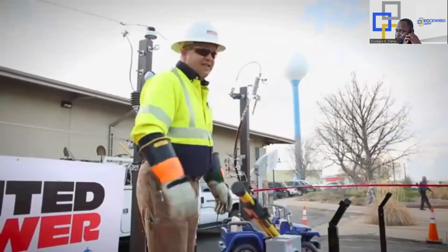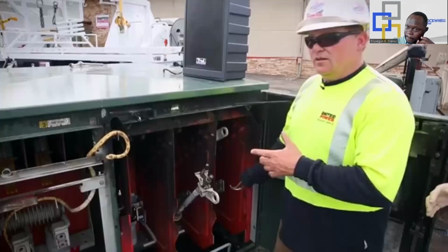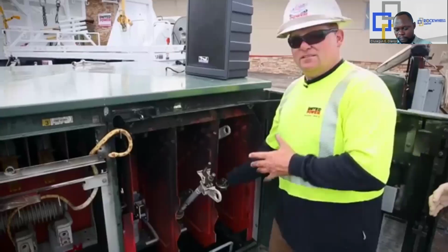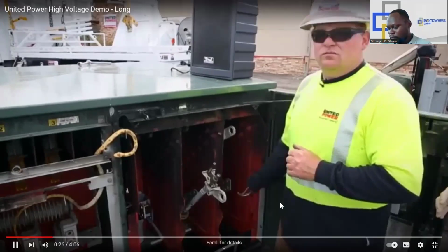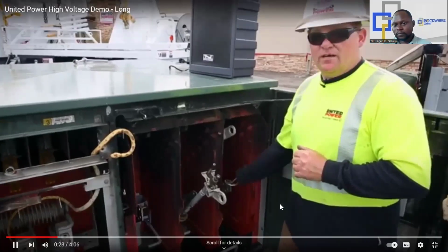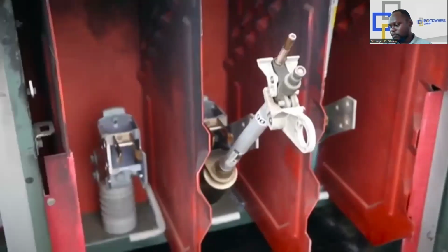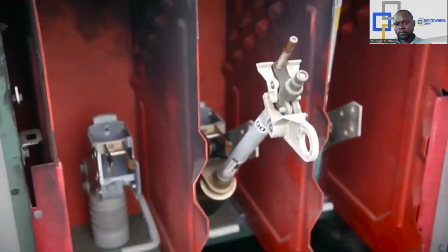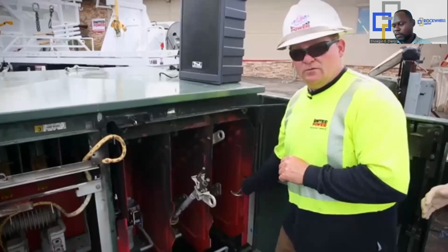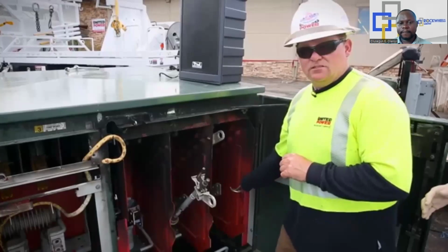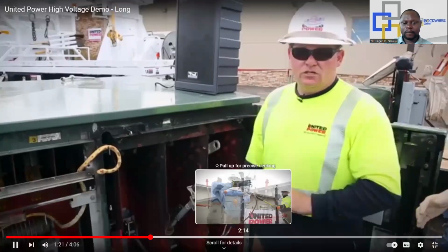Ten years ago, I was electrocuted working in an underground switch cabinet like this here. Normally, the bottom of this cabinet is dead, the top is energized. We crossed the conduit, we didn't mark in and out, so when we energized it, the bottom became hot. My mind was elsewhere. I was thinking about going camping and four-wheeling. I did not check voltage, I didn't have ground, I didn't test. I reached in the bottom of this cabinet when I saw a loose bolt and I went to tighten it. And I took 7,200 volts to ground at my hand and wrist. It came over your internal organs.